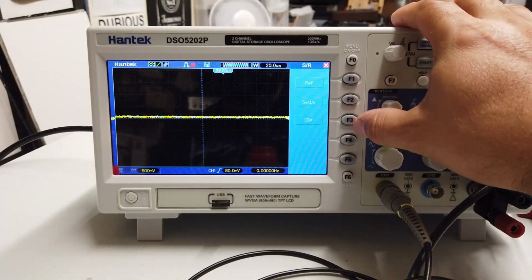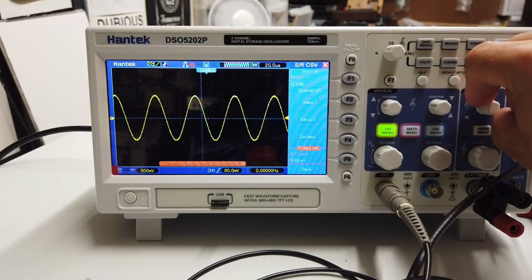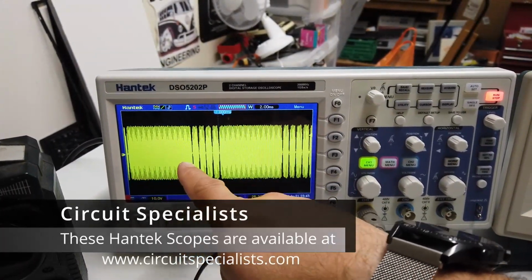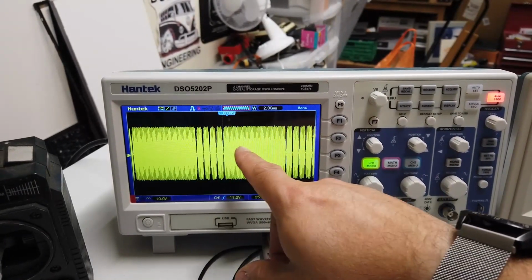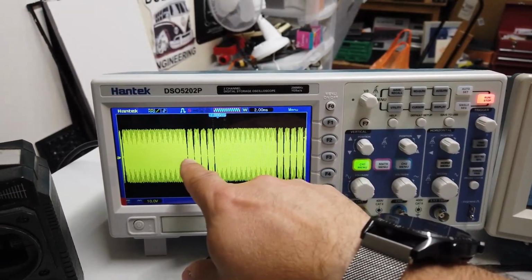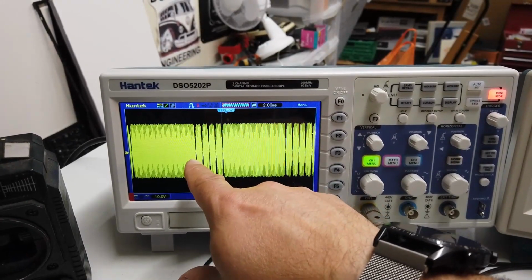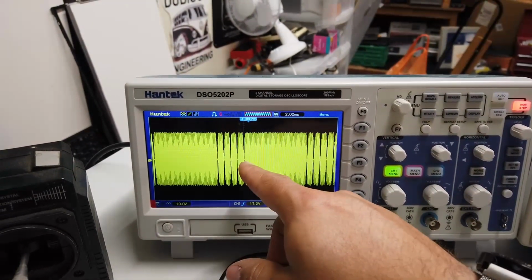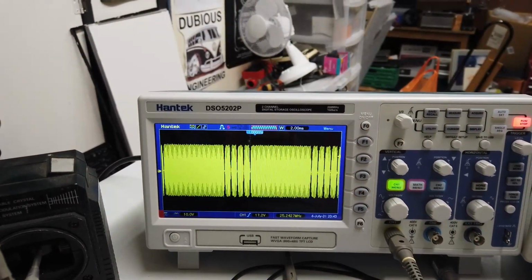And then you can scroll around that waveform and look at it once you've saved it to memory. It's actually quite good because you can see here the dense sine wave is the 27 MHz carrier wave. And then we have these 4 little lumps and then another portion of dense sine wave, 4 little lumps. And effectively, this is the encoding of the proportional radio signals to tell your car to accelerate, decelerate, however many channels your receiver might happen to be. So it's quite nice that you can get in there and see that kind of stuff.